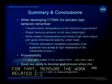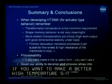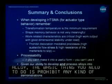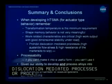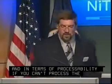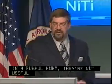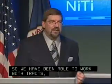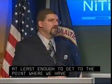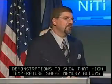And if you want to make a better high-temperature shape memory alloy, the basic thing you need to do is prohibit any kind of dislocation-mediated processes or deformation processes from occurring in the material. In terms of processability, if you can't process the alloys in a useful form, they're not really useful. So we've fortunately been able to work both tracks, alloy development and processing in these materials, at least enough to get to the point where we've run some demonstrations to show that high temperature shape memory alloys are actually viable today for some high temperature applications.